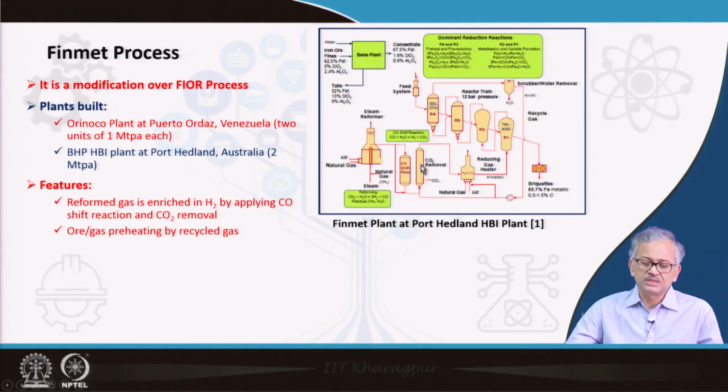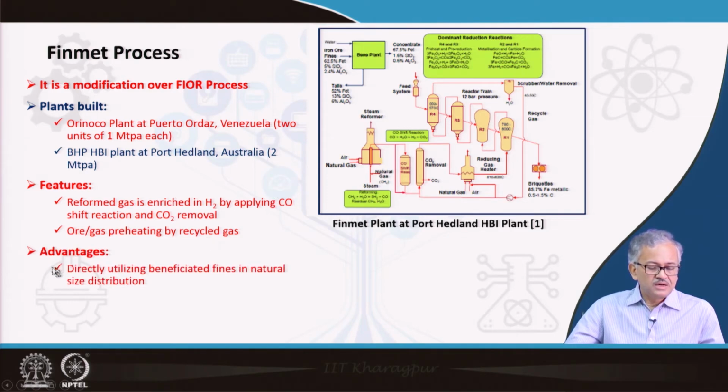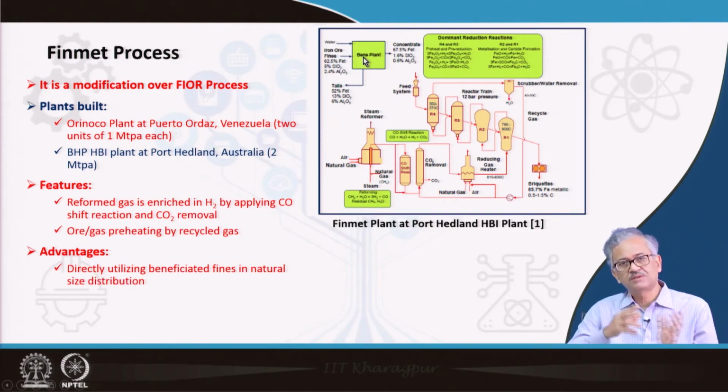Okay, and this ore, before putting into the reactor, you preheat with the recycled gas. This is one modification over the FIOR process. In the FIOR process it was not there. Also the FIOR process did not have the CO shift reaction and CO2 removal system, and ore and gas preheating by recycled gas was integrated in this process.